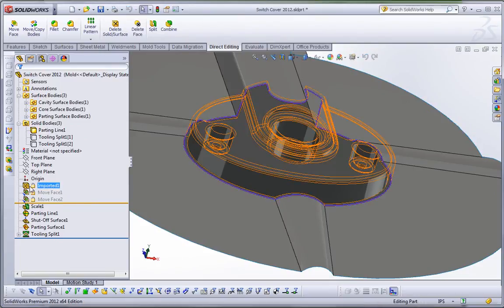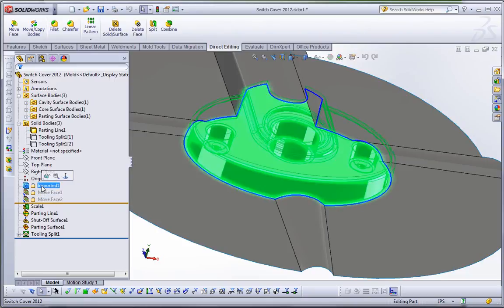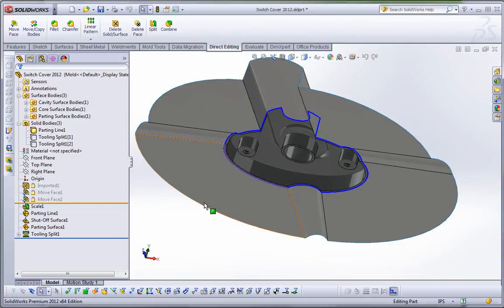So what that does is puts a padlock, the icon changes, and that prohibits any rebuilds. It's very similar to locking a reference in an in-context design. If you create a sketch that is in reference to another assembly, you can lock the reference so it prohibits updates from coming through. In the same way, the feature freeze doesn't rebuild.